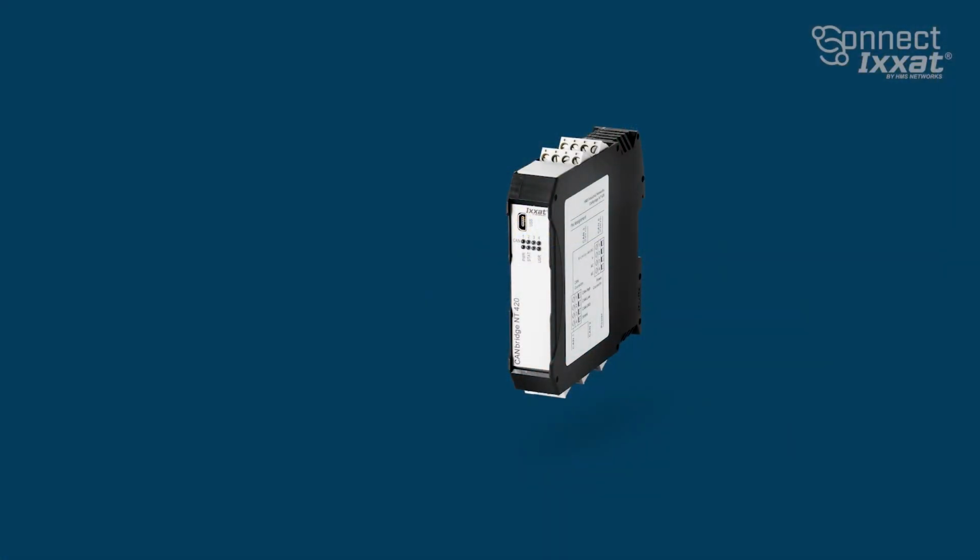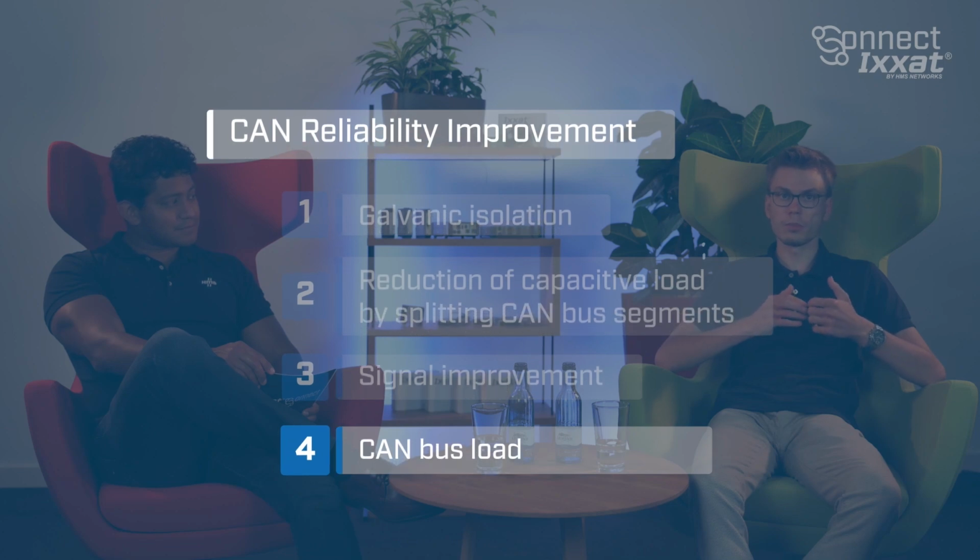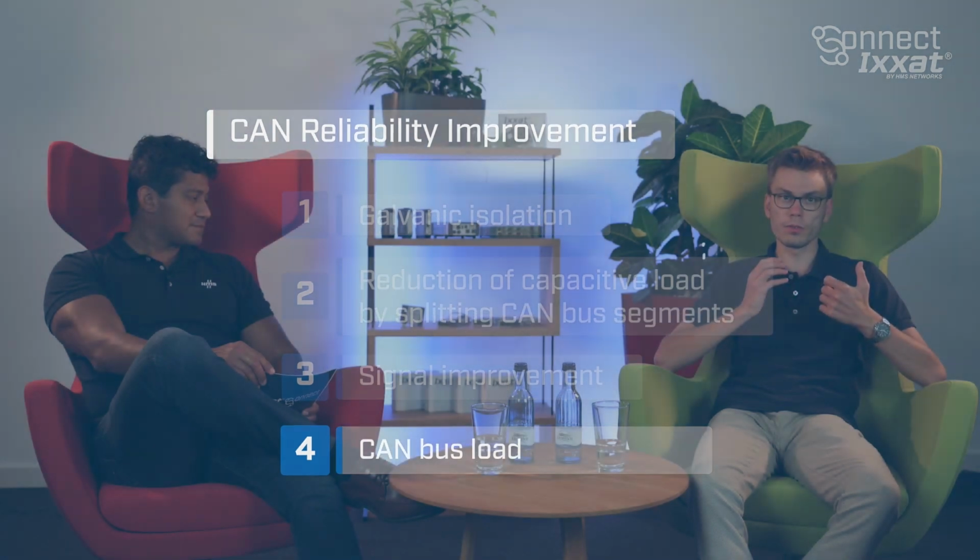And if there's a need to extend the bus beyond the standard length? When you have the case that you want to exceed the maximum bus length, you can use a CAN bridge as a solution. It allows to extend the network while maintaining the signal integrity, effectively increasing the operational performance without degrading anything.